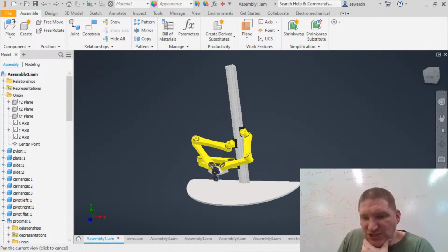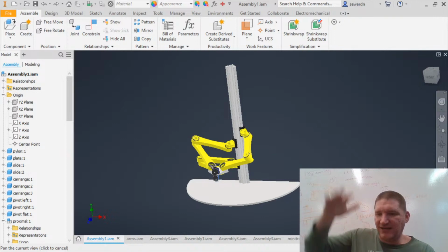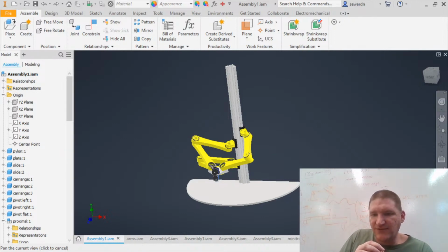Okay, so somebody, J.K. Lee, I had built a quick draft based on your idea of the Z position, quite hard to define with a 15-degree tilt angle. Yeah, so I think 30 would be the smallest I would try. If 30 doesn't work, I might have to go to 45, and as the angle gets bigger, I lose more capabilities in where I can reach, and I have to use longer rails and that kind of stuff. So I'd be curious. Maybe you guys can message me with your test or video of it. I'd like to see how good it is and what it looks like. I'd love to see that.